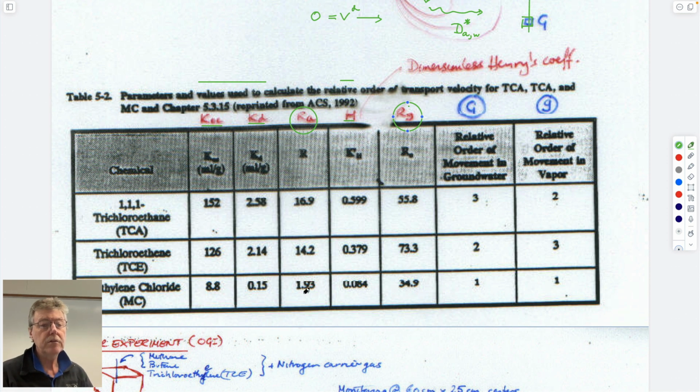So it means that the lower the retardation coefficient, the earlier the arrival. So in the saturated zone, we're governed by the aqueous retardation coefficient. The fastest moving phase dissolved in water is methylene chloride. The next fastest is this, and the slowest is this, most retardation. So the arrival time in the groundwater piezometer will be first, second, and third. And that's just according to the magnitudes of the retardation coefficients increasing monotonically through these 3 different compounds.